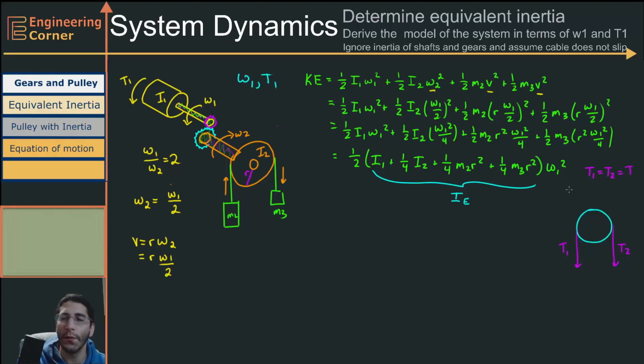But that's because we were always ignoring the mass and the inertia of the pulley. So we would say mass is equal to 0 or our inertia is equal to 0. And that would give us the moment equation: I times our angular acceleration is equal to the sum of the moments. If our inertia is equal to 0, this side of the equation is going to be 0. And let's just say that this has a radius of r.